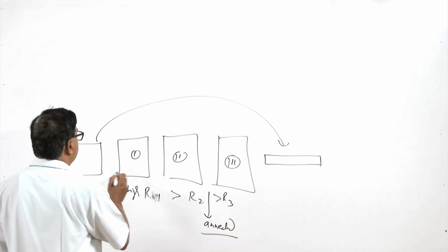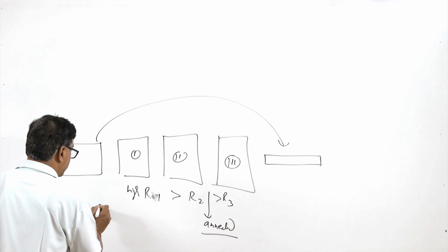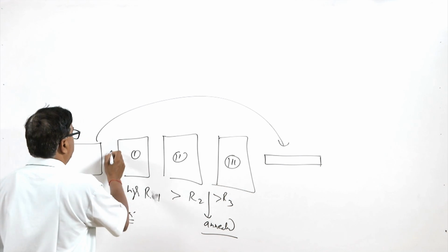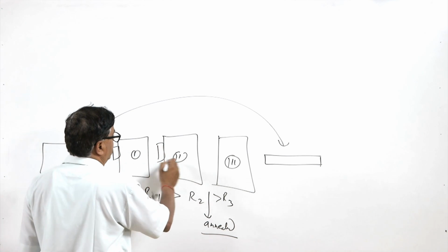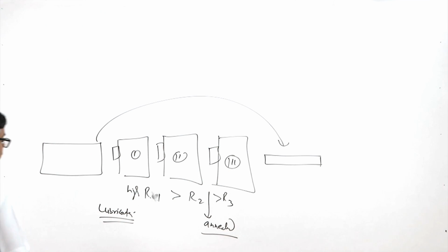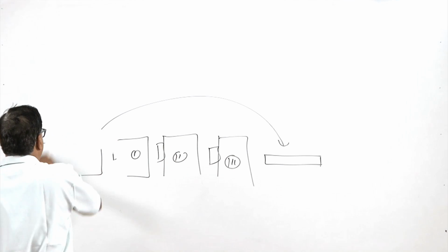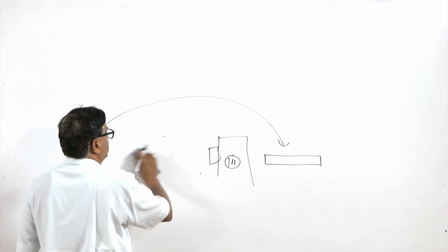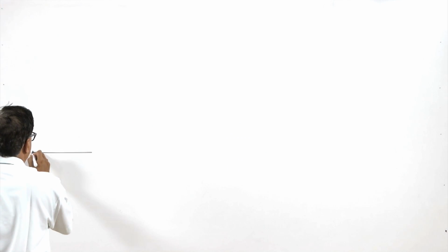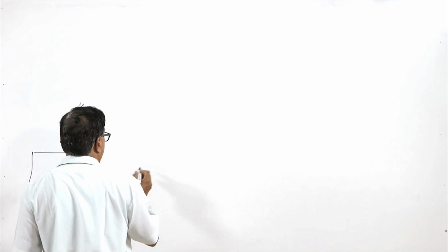In addition to drawing through the different stages, what we need is lubrication. Before each stage of drawing, lubrication is done of the wire or of the bar which is to be drawn. Now I'll draw a schematic to show how the drawing is carried out. Here is the mechanical arrangement which will be used for pulling the carriage.